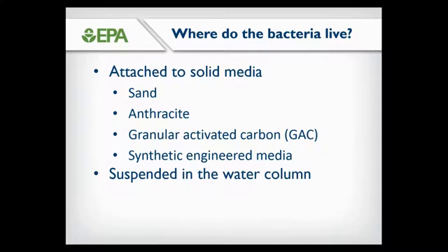process. And going back to the attached growth processes, when they're attached to media hydraulically, these units are typically operated in one of two ways. They're either operated in a downflow mode, so hydraulically very similar to a typical rapid media drinking water filter, or these units can be operated in the upflow mode as a fluidized bed process. For the remainder of this presentation, we are going to look at biological contactors that are operated in the downflow configuration.